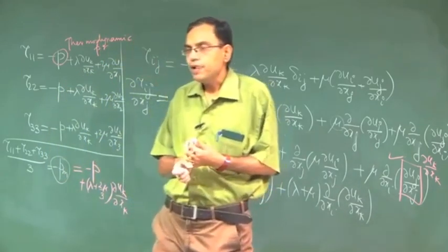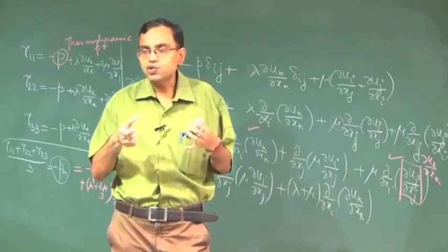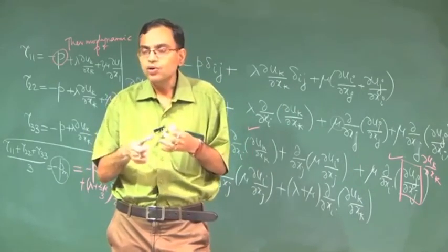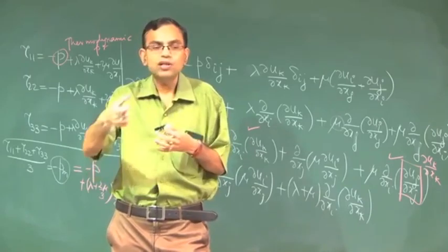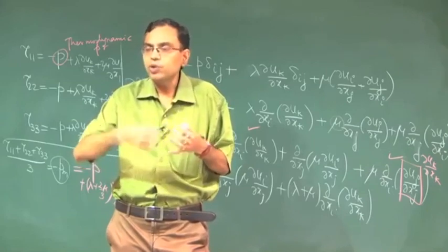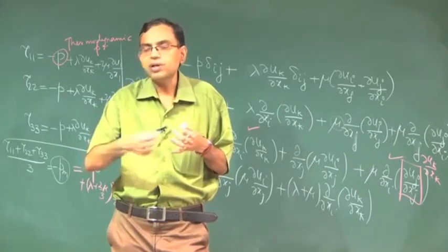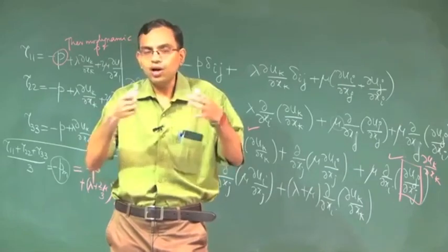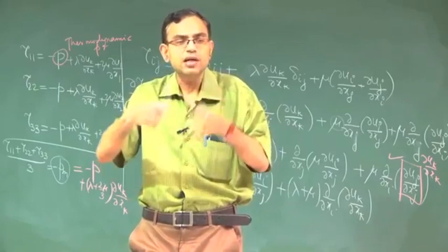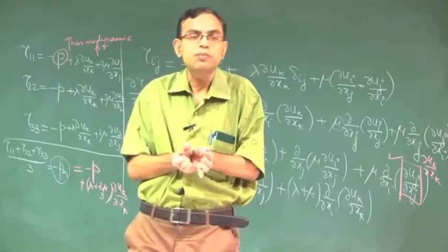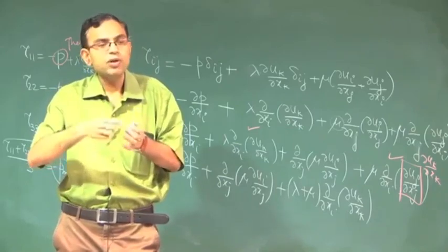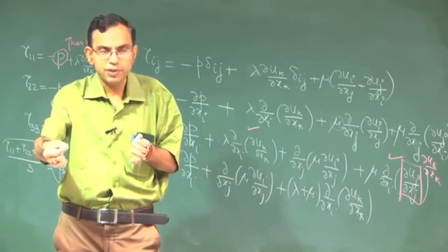See, normally the fluids relax to a state of local equilibrium very fast. So, if you impose a force on the fluid, it will relax to its new equilibrium state as a consequence of that force very rapidly. All the degrees of freedom will instantaneously be converted to the translational degrees of freedom, and that is how it comes to an equilibrium everywhere. So, this means that the mechanical pressure will become the same as thermodynamic pressure.